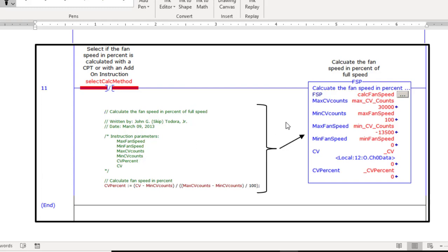But I made it available as a ladder instruction, as a function block instruction, or you could use it in structured text. So in the Studio 5000 software, we can do user-defined instructions. I actually did that in Lab 1 with the random number. That was a user-defined instruction. CCW has the same functionality, and my plan is to actually show you how to do that in CCW.